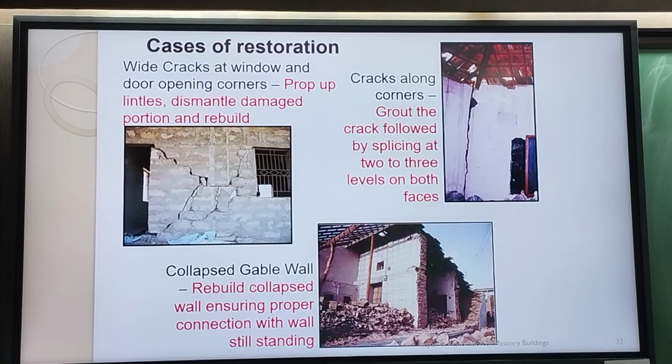So to put this back in the original state or better state, actually this particular wall would have to be dismantled in a step-like manner. This wall here also would have to be dismantled. See, this is already in a step-like situation. So then you start building this along with this triangular portion.